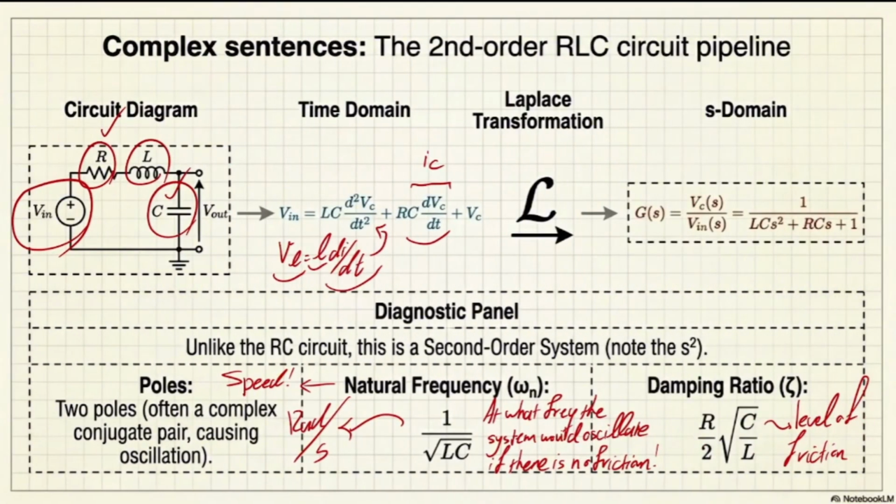But what would happen if we do have the derivative to the power of 2? So at this point, we do have another scenario. It means that rather than just the capacitor C and resistor R itself, I do have the inductor. Everything would be the same for C and R, but we do have another one, which is the inductor itself. And the inductor is going to follow this formula. The voltage of the inductor is L times di divided by dt. Di again is di C. So if you put it over here, rather than just derivatives to the power 1 or the first order, we do have second order. So at the end of the day, your formula is going to be like that.